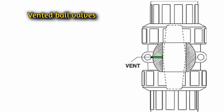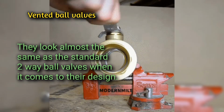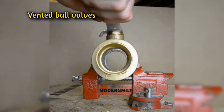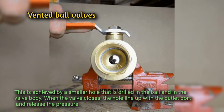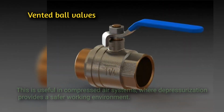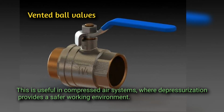Vented ball valves. They look almost the same as the standard two-way ball valves when it comes to their design. The main difference is that the outlet port vents to the environment in the closed position. This is achieved by a small hole that is drilled in the ball and in the valve body. When the valve closes, the hole lines up with the outlet port and releases the pressure. This is useful in compressed air systems, where depressurization provides a safer working environment.